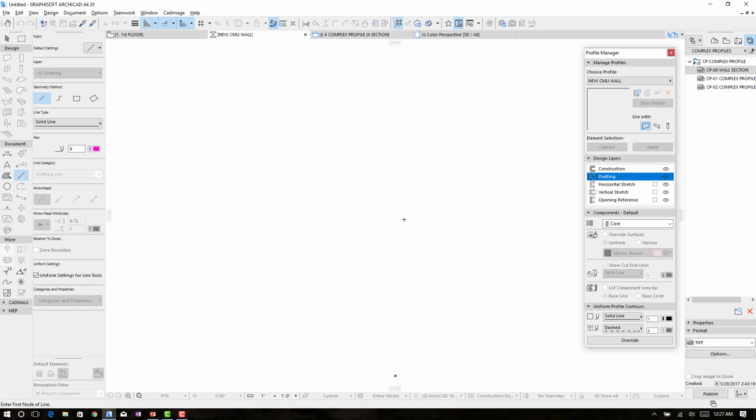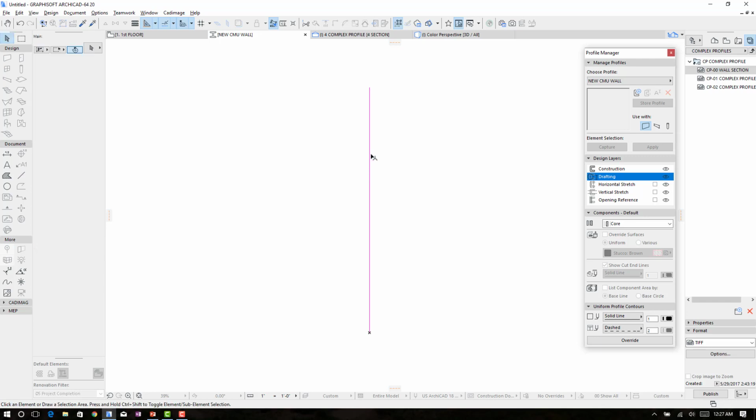So next, we'll start laying out the wall with the line tool, located here. Click on that. Set the wall, snap it, and set it at 10 feet. That will give us a 10-foot wall to start out with.